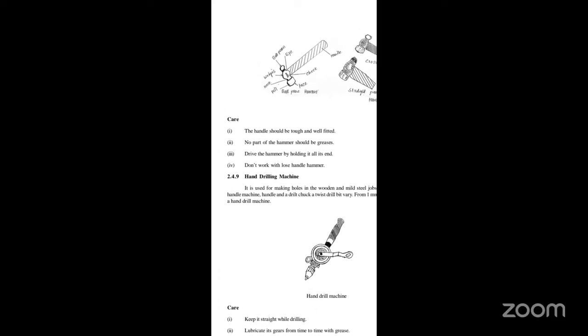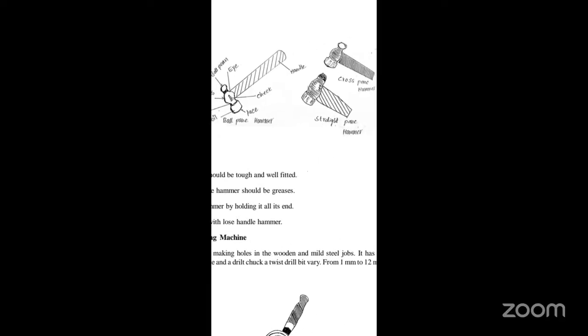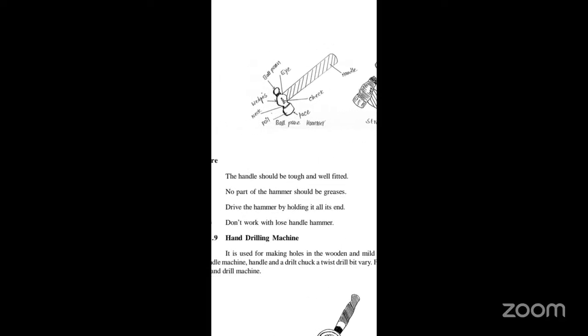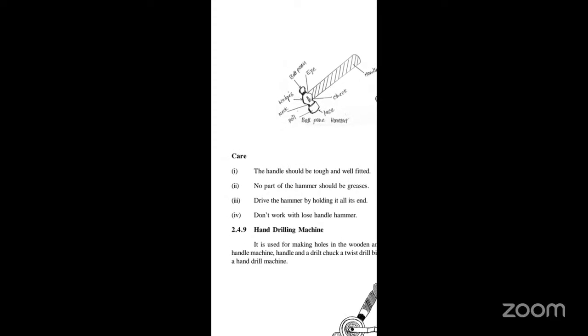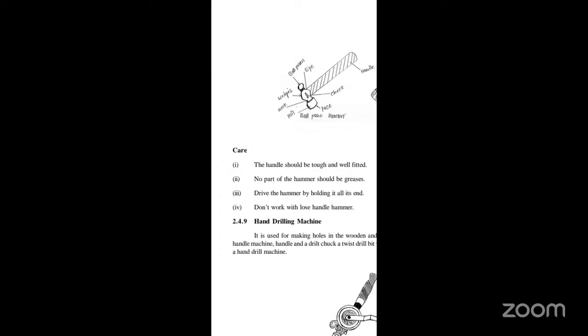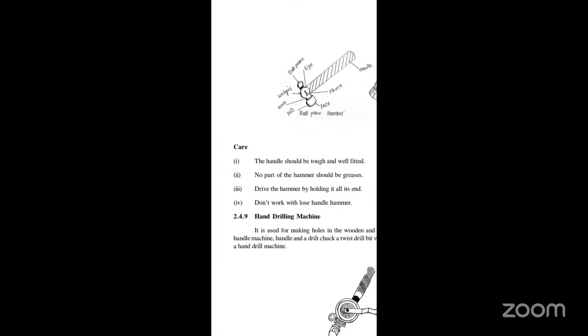Now, care. What are the different types of hammers shown in the figures? See how it is. Now, care. The handle should be tough and well fitted. No part of the hammer should be greasy. Drive the hammer by holding it at its end. Don't work with a loose handle hammer.